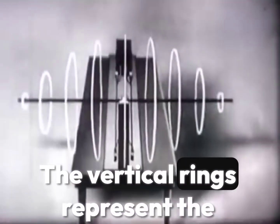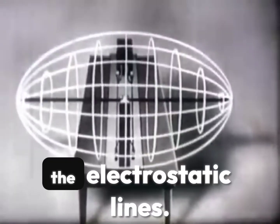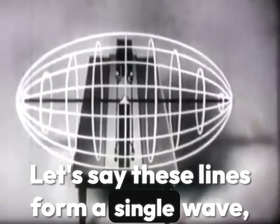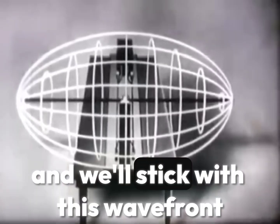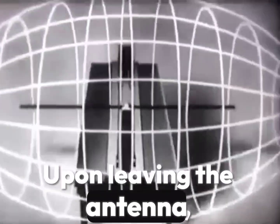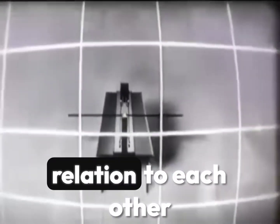The vertical rings represent the magnetic lines. The horizontal rings, the electrostatic lines. Let's say these lines form a single wave, and we'll stick with this wavefront as it is radiated into space. Upon leaving the antenna, the pattern enlarges. It stretches, yet the magnetic and voltage lines retain a fixed relation to each other and to the Earth.